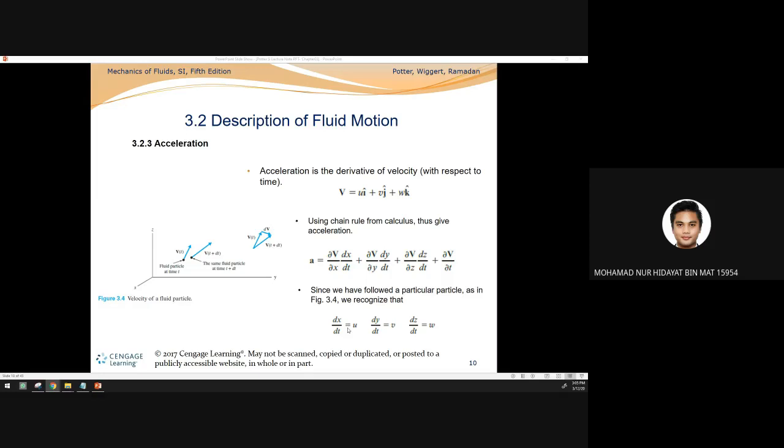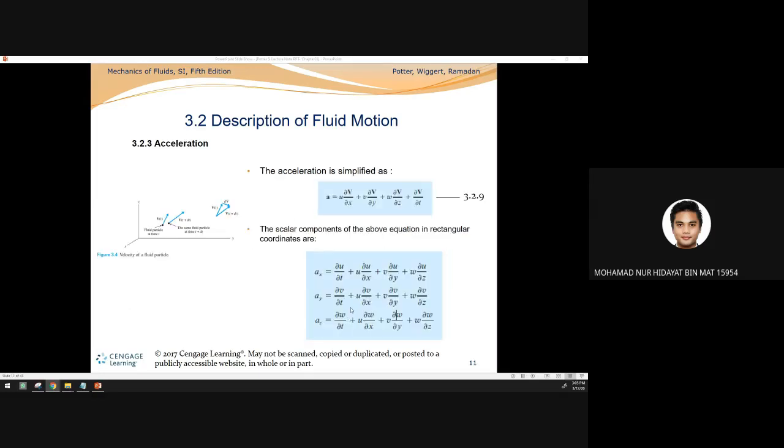In this part, we are going to study and understand each term very carefully. So when the question asks for a few parameters, you will identify the values of u, v, and w. You need to remember and understand the formula given here. This is acceleration in terms of u, v, and w. This capital V is what we call the total velocity vector.